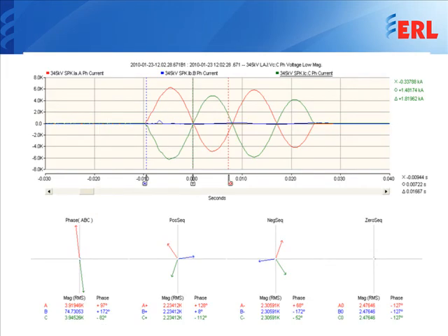Now, if we look at the symmetrical components as described by the circuit, we are supposed to only see two sequences, positive and negative sequence components. Very high values we should expect on these components. We can see about 2200 amps on positive sequence and about 2300 amps on negative sequence, and about 2 amps on the zero sequence.